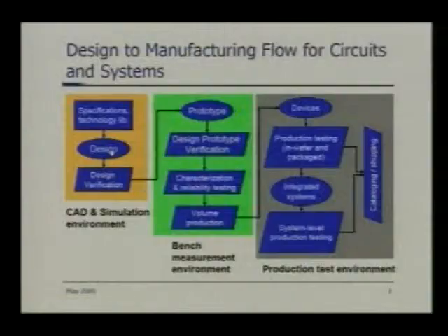Using these, you design, and as long as you are within the simulation environment, you simulate, re-simulate, simulate over again to make sure that whatever gain specification, frequency specification or noise performance specification you are given in the beginning, you meet them for the given technology library.